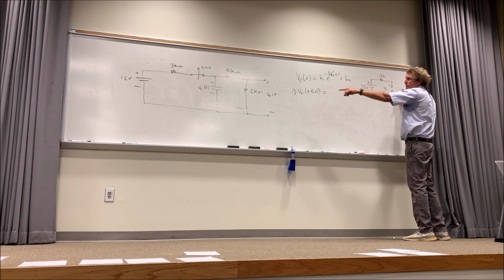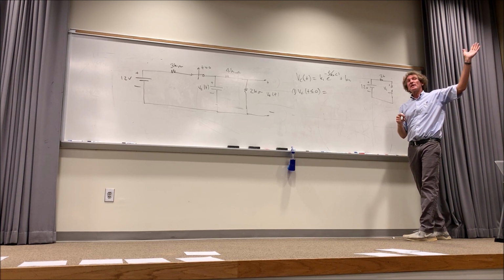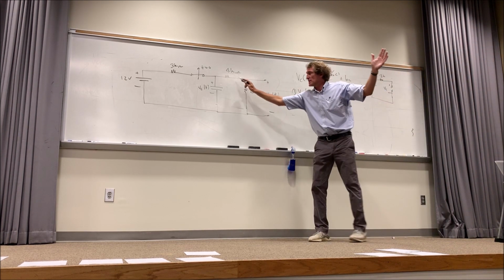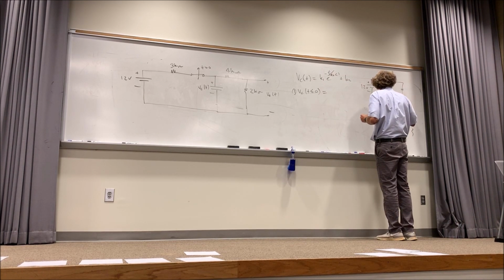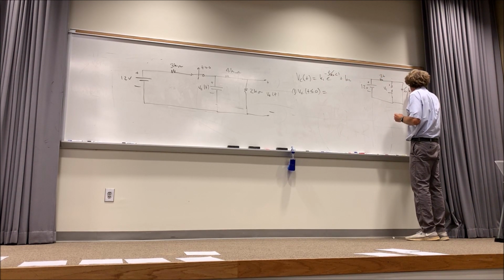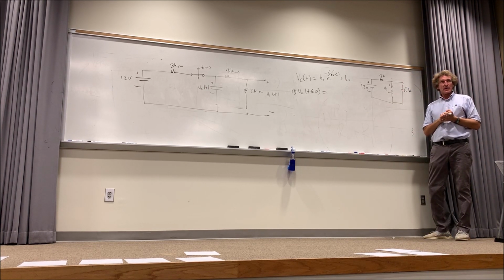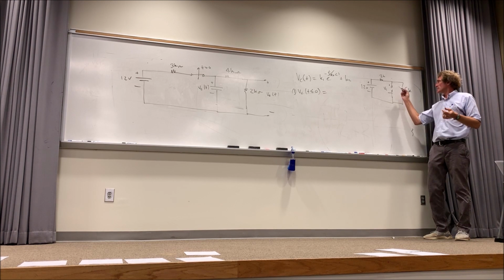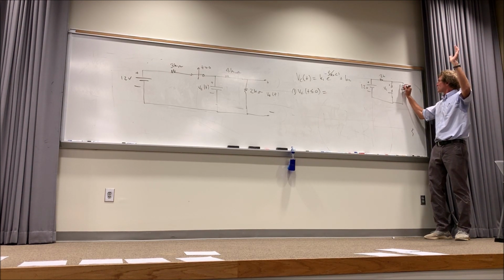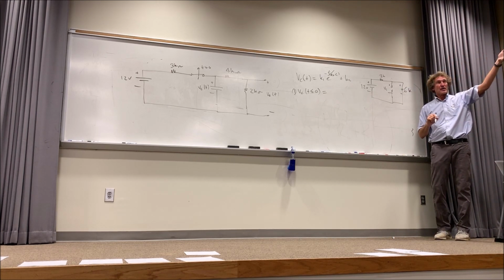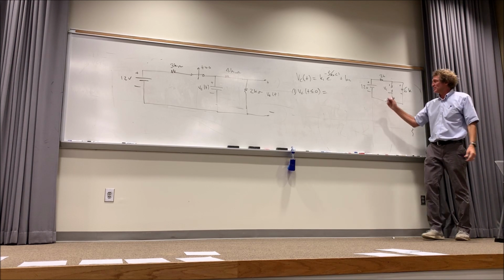Then, can I put the 4K and 2K in series? How many see that? Does anybody not see it? These 2 are in series, are they not? I can replace that with 6K. So what is the voltage right here going to be? How many realize this voltage is the same voltage across that 6K? Well, what's the voltage across the 6K? You're using voltage division.